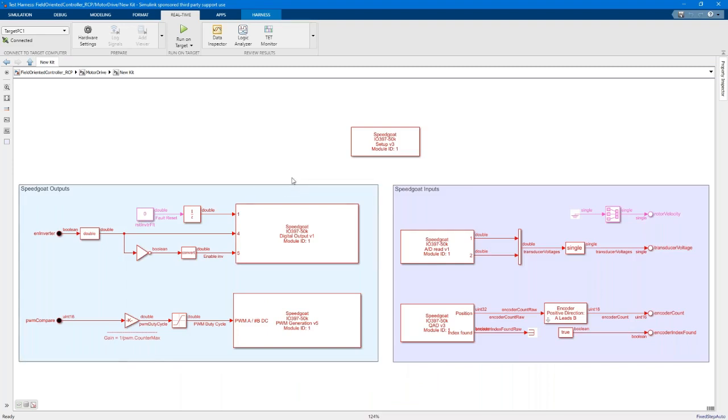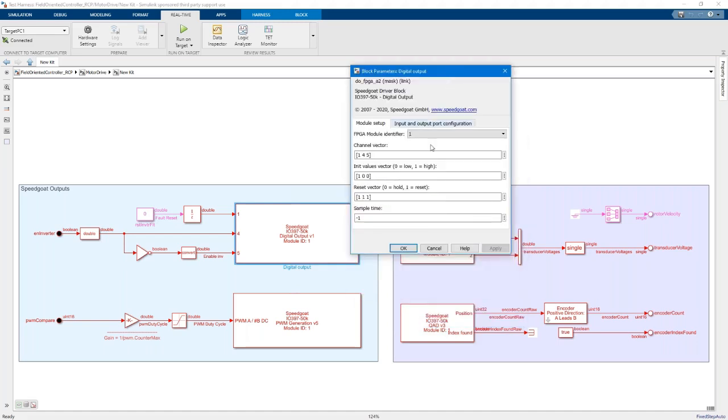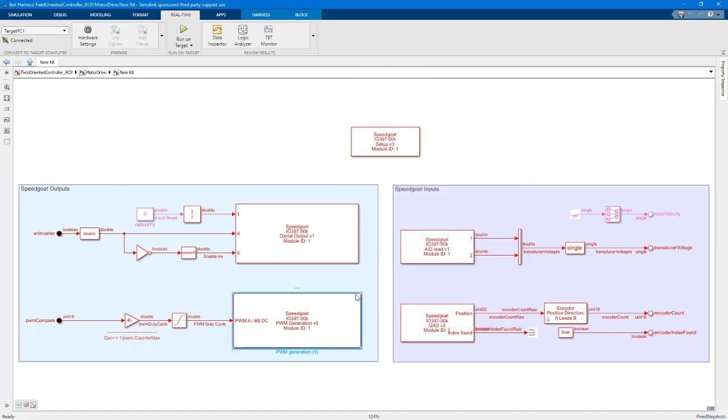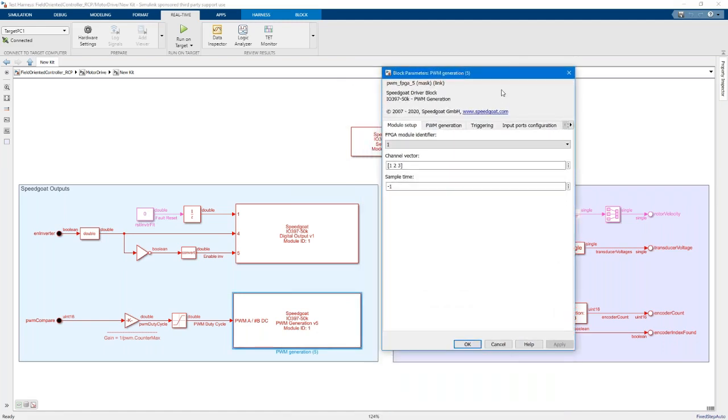And what we immediately will see, and both Naga and Spooty have talked about this, is the I/O blocks. So let me just click on one of these I/O blocks. Yeah, this is the setup block, but let's go, for example, into the PWM generation block. So this block talks actually to the FPGA module, and we will all agree that PWM signals are in the microsecond or sometimes even nanosecond domain, so you need a very quick execution for these pulses, and this requires really powerful hardware, and in our case, we are using an FPGA for that.